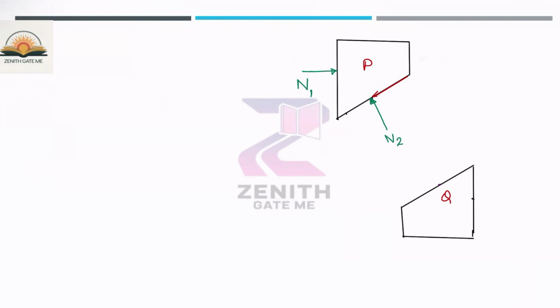And this block has a tendency to move in the upward direction, and this surface will move outward. So that means the friction force will act downward. So let us suppose the friction force is nothing but mu into N2. What will be the resultant of these forces? Let us suppose the resultant is R. Now, this resultant of these two forces makes an angle of phi from the normal reaction, which is called the angle of friction.